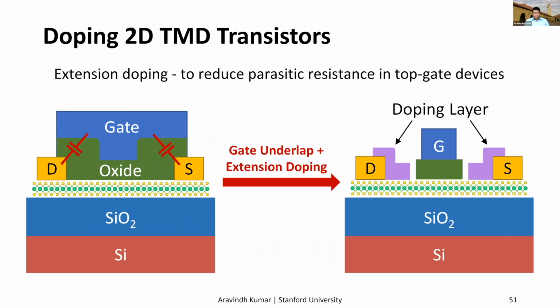Yeah, thanks for the question, Kwan Ho. For your first question, for most contacts on this monolayer MoS2, the carrier injection happens mainly at this contact edge shown here. So even in a top gate case, if we could gate this vicinity very well, by having this gate overlap, I think we will get decent contact resistance.